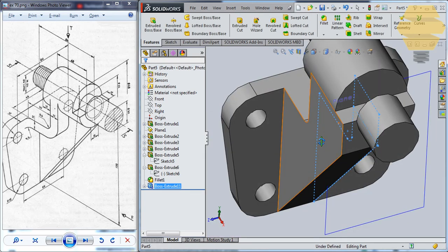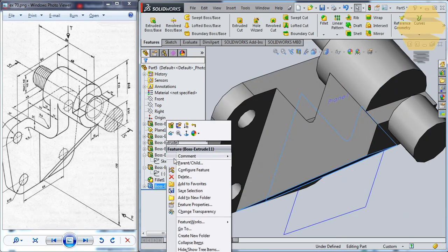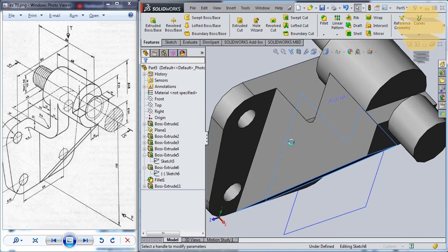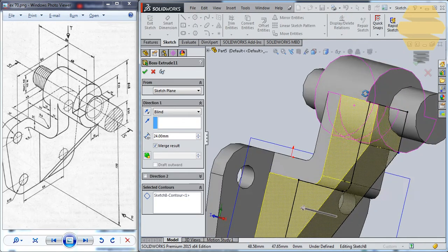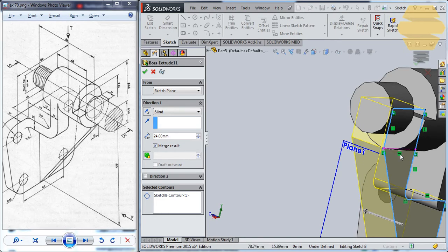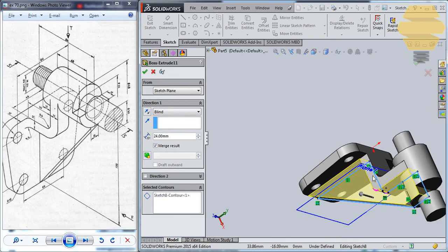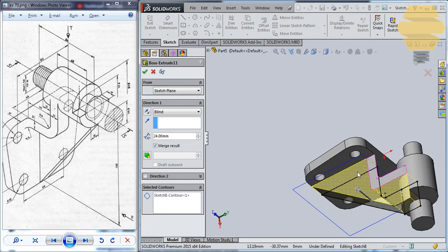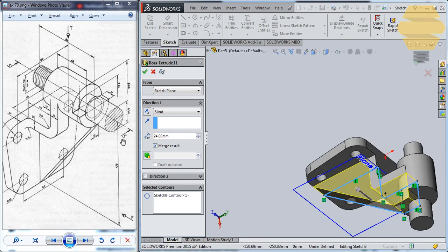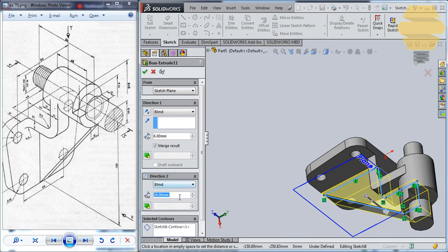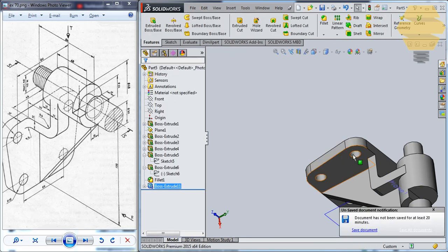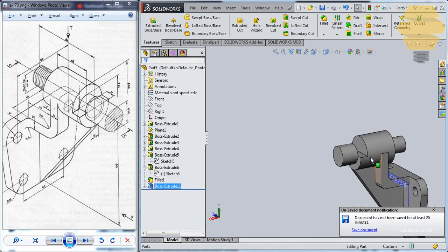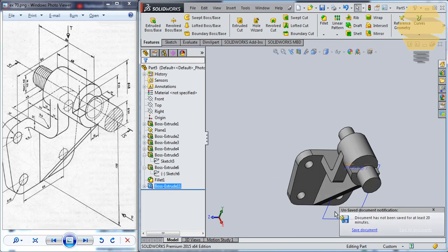So previously there was no problem with the sketch. The problem was that, as you see over here, when you give extrude here, it creates a gap over here, and that's the reason it's not able to create. So what we do now will be to create on one side 6 and on the other side 6 as well. So now we have this complete here.